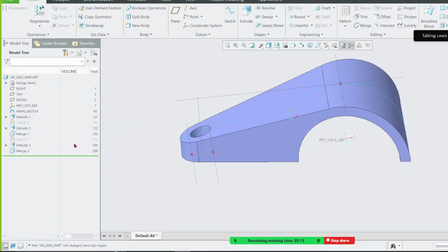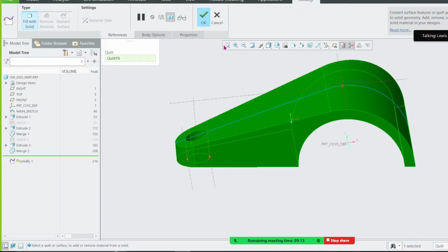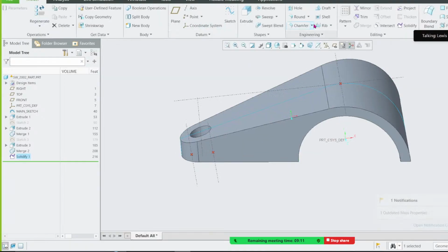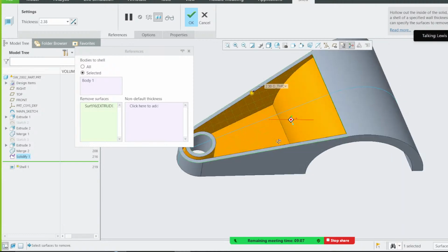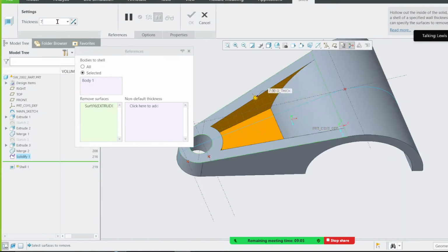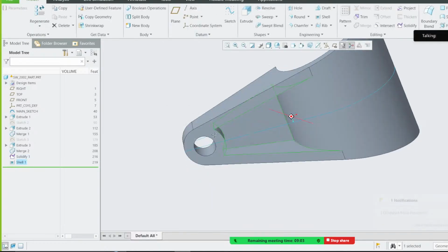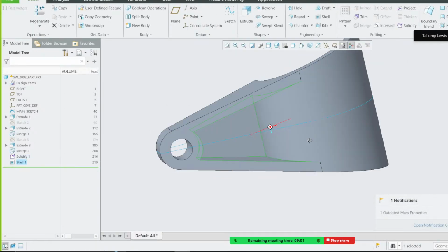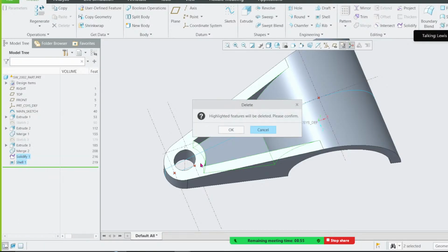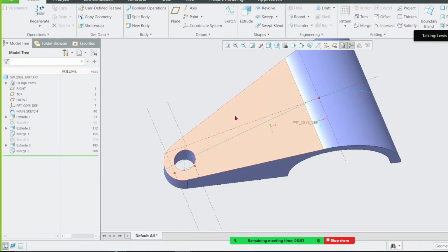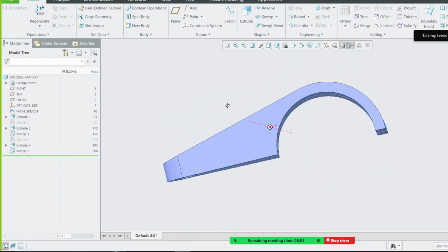If you convert this to a solid, those people who prefer solid modeling, you can just use a shell. When you shell that, you create that automatically. If you do 7 here, you see, shell, and you get it. But for me, I'm not using solid. I will say today is an advanced surfacing. Let me show you how you can create that using a surface.